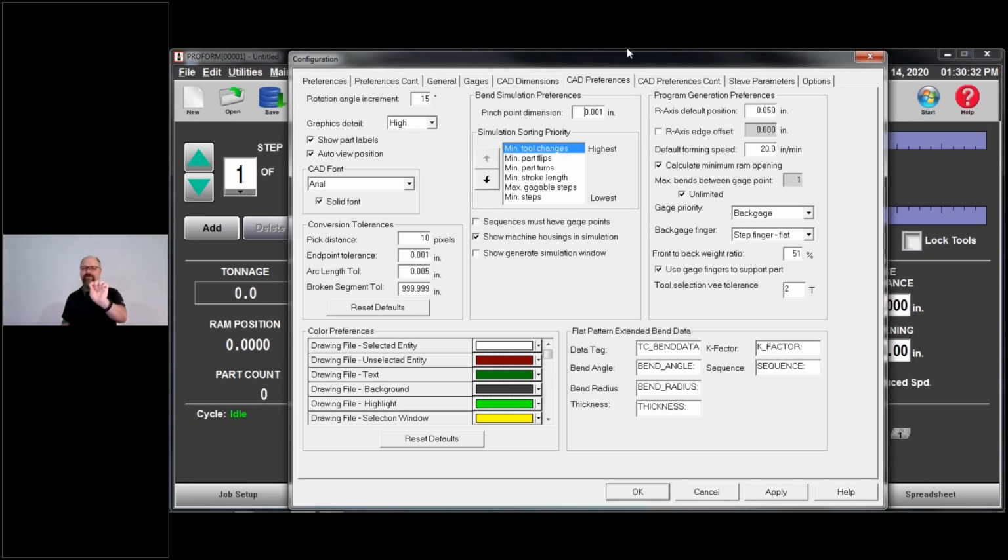The software is going to try and keep that most number of bends over here first. So it's going to try to do 1, 2, 3 here and then 4, 5, 6, 7 over here, or 1, 2, 3, 4 here and 5, 6, 7 over here. Minimize the number of times I move between tools. Again, fairly rare issue for that to happen.